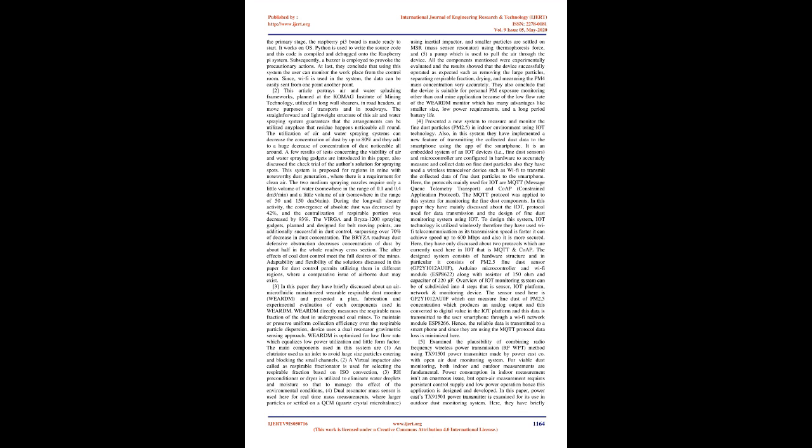All the components mentioned were experimentally evaluated, and the results showed that the device successfully operated as expected, such as removing the large particles, separating the respirable fraction, drying, and measuring the PM4 mass concentration very accurately. They also conclude that the device is suitable for personal PM exposure monitoring other than coal mine applications because of the low flow rate of the wearable monitor, which has many advantages like smaller size, low power requirements, and a long battery life. 4.